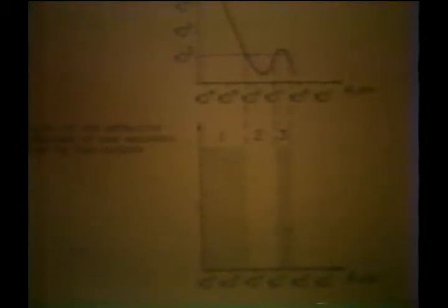There are two possibilities for the formation of new emission sites under the plasma. The first one is an explosive point in the field of the ion volume discharge at cathode. The second one is a breakdown of dielectric films and inclusions after charging them by the plasma ion current.